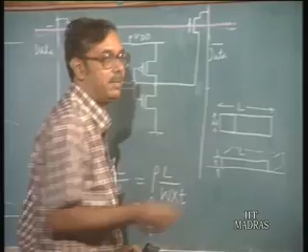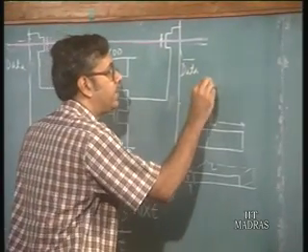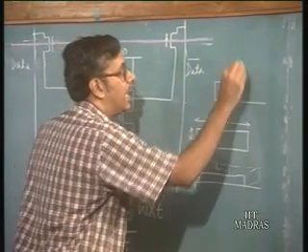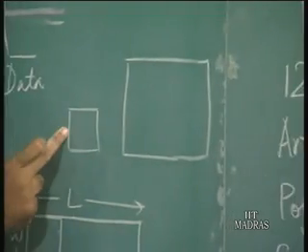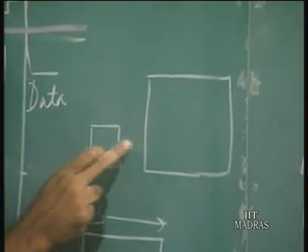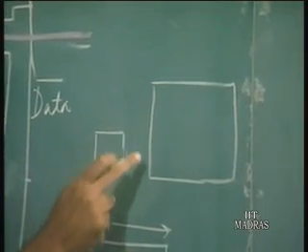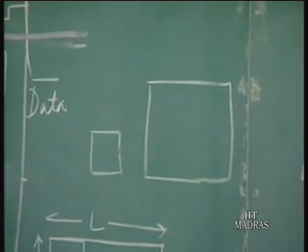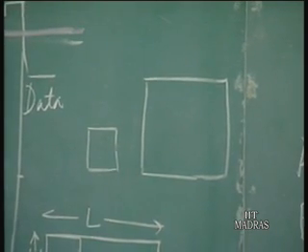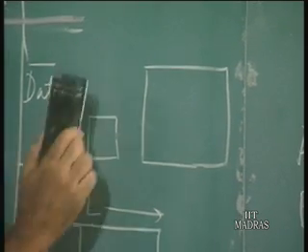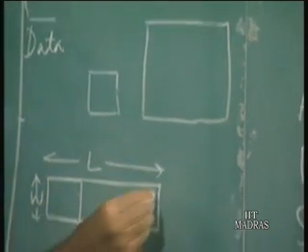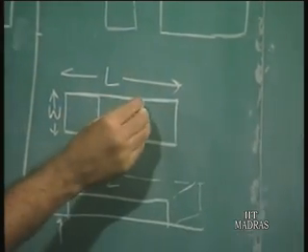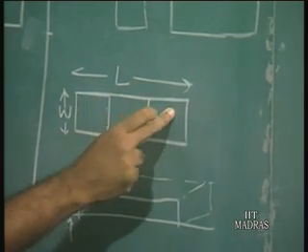So, if you take the same thickness of the same material and you have a small square or a large square, the resistance from one end of this line to the other is the same irrespective of whether you have a big square or a small square. So, it does not depend on the size of the square. So, in this case the total resistance is now going to be given by how many squares you have.